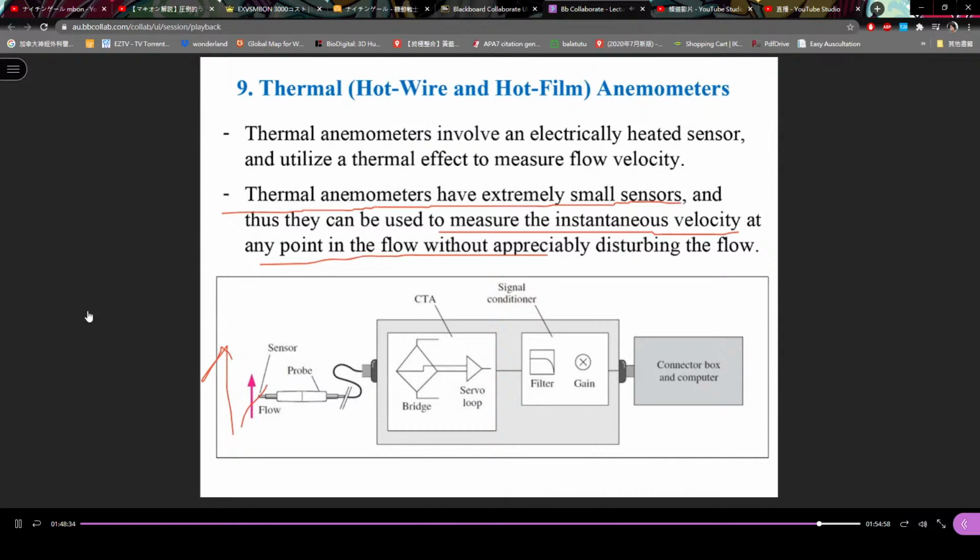It's a very, very popular thermal anemometer. We don't need to derive any equation. It is produced by a manufacturer, and you simply measure with it. And nowadays you can find displayed data and recorded data. I think this is all the flow rate measurement meters I introduced. How many? Maybe 8 or 9. I couldn't remember.